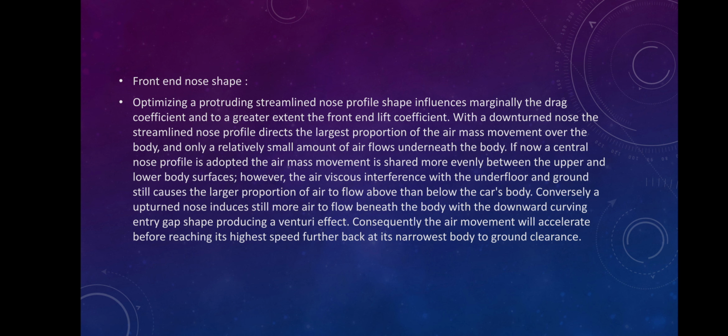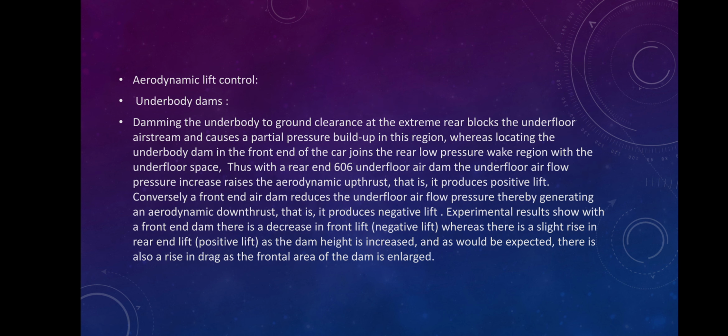Conversely, an upturned nose induces still more air to flow beneath the body, with the downward curving entry gap shape producing a Venturi effect. Consequently, the air movement will accelerate before reaching its highest speed further back at the narrowest body to ground clearance.